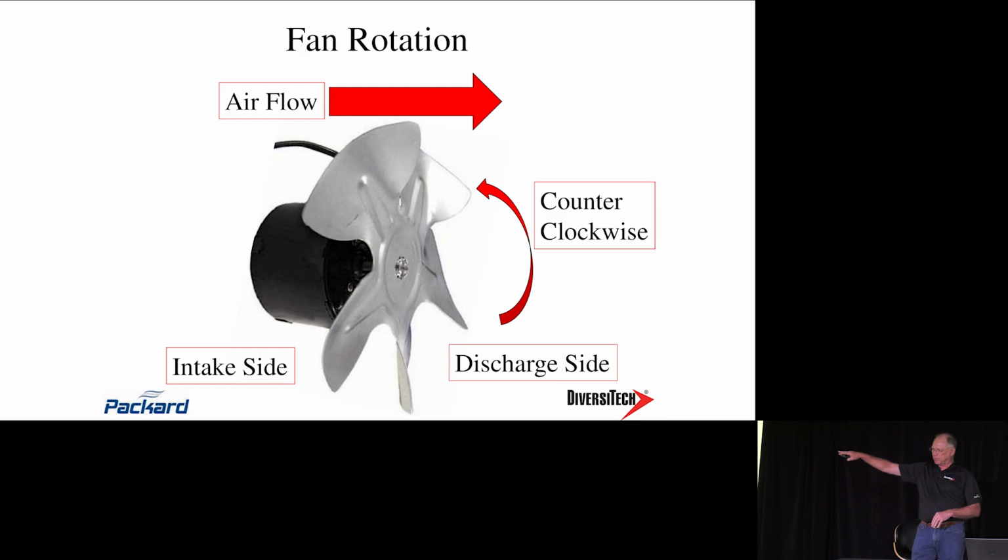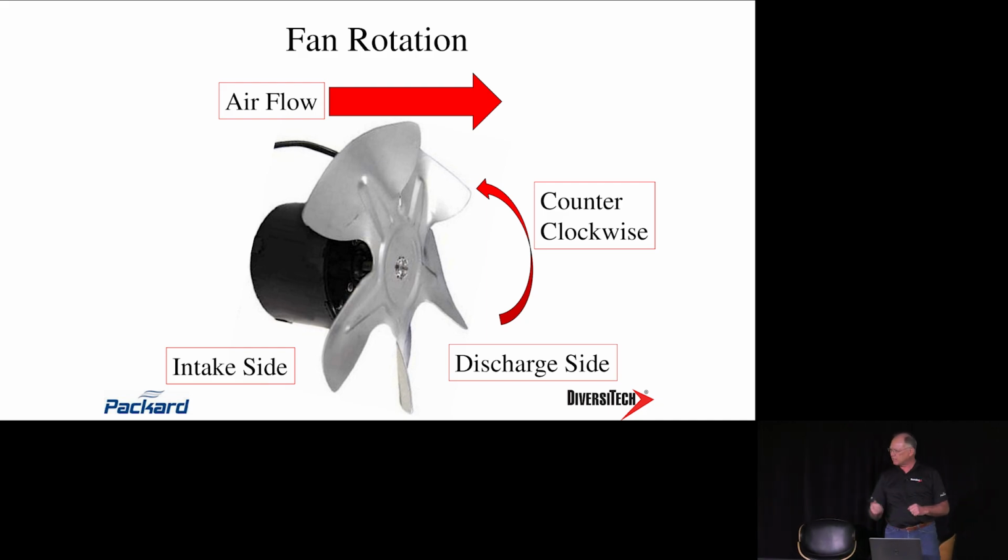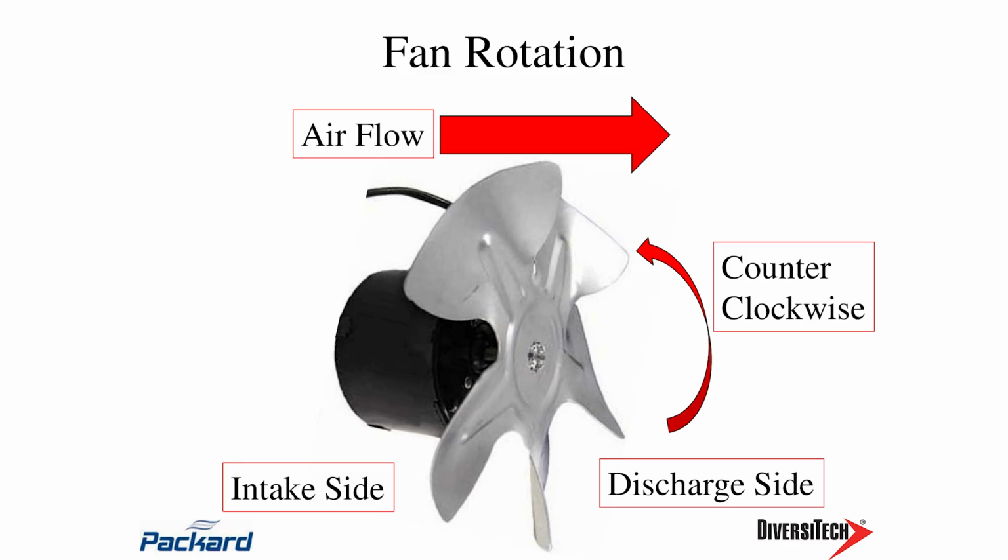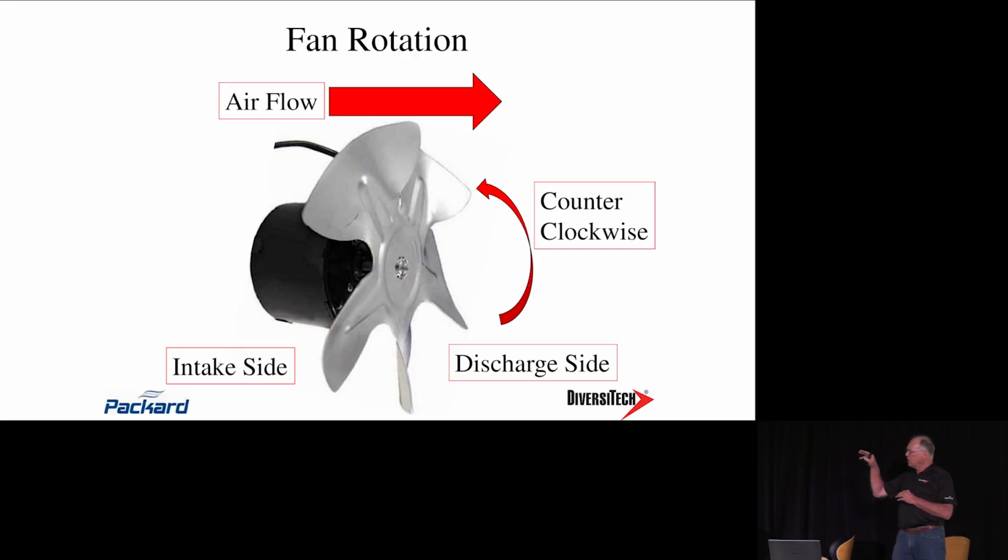So when we look at a fan blade, this is on a refrigeration application. It's taking the air, bringing the air in from one side, pushing it through the other side. Now, an axial fan is affected by static pressure. Its performance is affected by static pressure. So free air, with no static pressure on the fan blade, results in the least loading on that motor. Does that make sense? If it's free air?